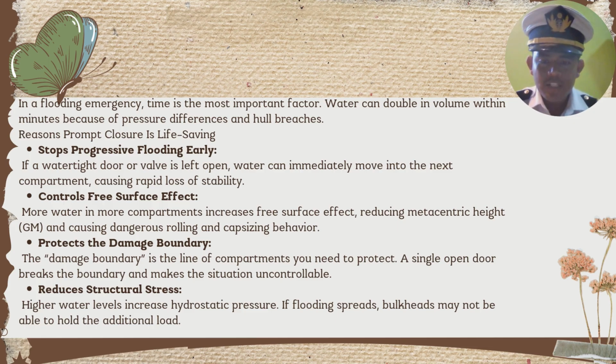In a flooding emergency, time is the most important factor. Water can double in volume within minutes because of pressure differences and hull breaches. Reasons prompt closure is life-saving. The first one, stop progressive flooding early. If a watertight door or valve is left open, water can immediately move into the next compartment, causing rapid loss of stability. The next one is control free surface effect.